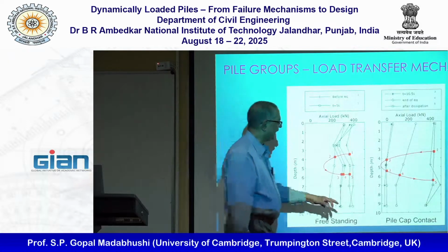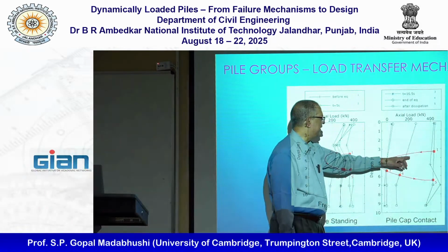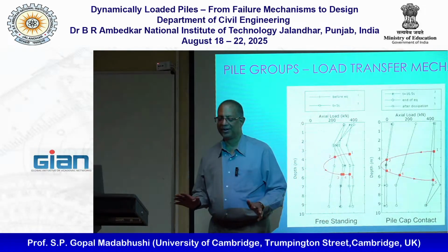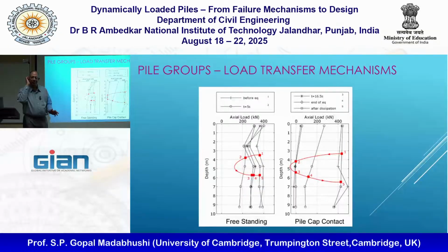Whereas when the pile cap is in contact, the piles completely don't carry any load. So who's carrying the load? The pile cap, right? So whether the pile cap is free or in contact makes all the difference on the load the pile is going to see. From equilibrium consideration, this is right because somebody has to support the load. Whereas here I got the pile cap to carry all the load, so the piles are completely unloaded during the earthquake. It's one really good construction practice.